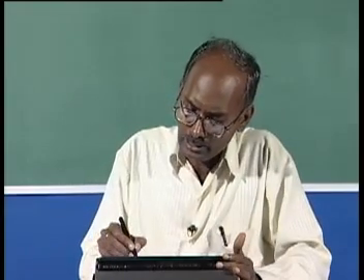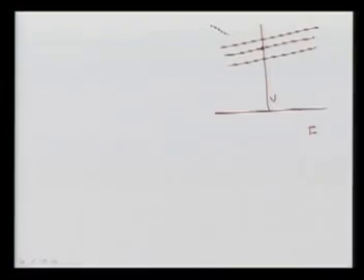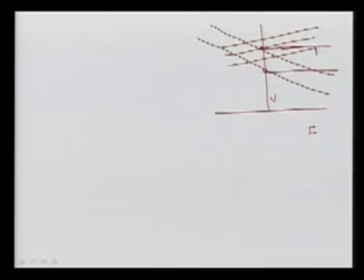Now let's suppose your system load line is this. If the system voltage is reduced and more load is added, what will happen? If there is no compensator, it was operating at this point, now it is coming here, and the voltage drop in the system is this much, that is delta V. But if you have some compensator with this characteristic, what will happen?